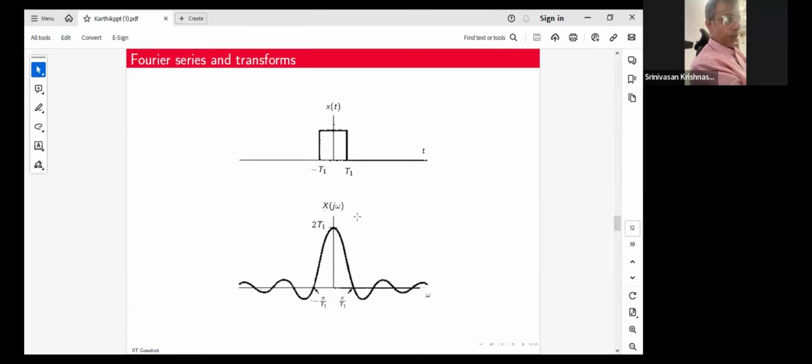The moment you have a frequency response, you're always talking about a linear system. When you go into the nonlinear portion of your triodes or diodes, you cannot have a frequency response at all there, so you cannot talk in terms of attenuations. A uniform drop in your frequency response is something you typically do not want. It's like you have a pole on a transfer function that occurs much before the attenuation starts, and you do not have any more poles in the period in which it is attenuating.